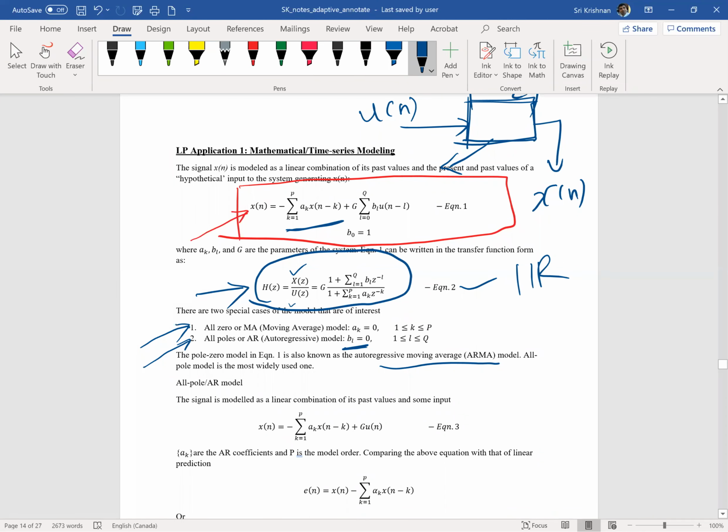When we say it's an ARMA model, we know it's related to some sort of filter theory we have seen before. It's a pole-zero model. Now, all your knowledge and understanding from pole-zero diagrams and the Z transform come in very handy, because the filter coefficients which we have seen before are starting to behave like model parameters.